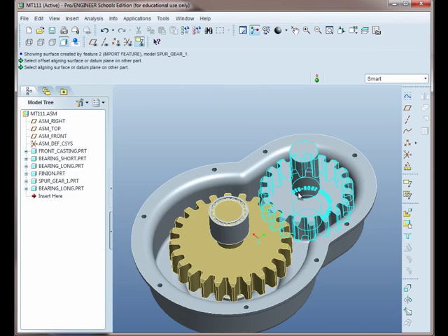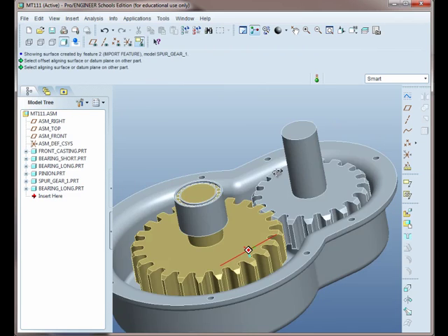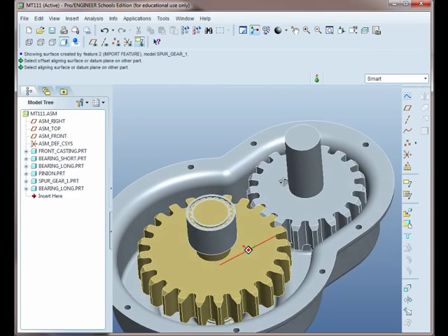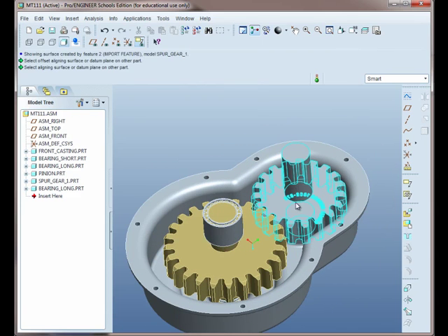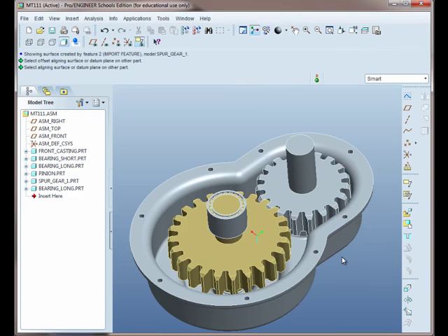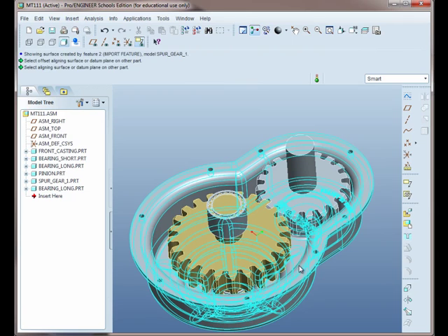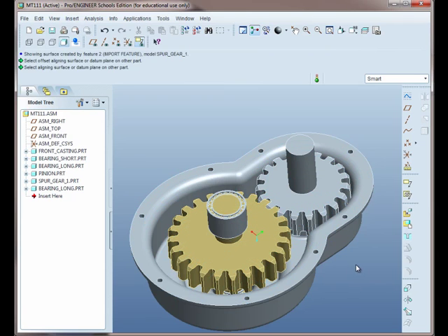The other bearing will drop in once we have the rest of the assembly surrounding it, because that one actually darts out a little bit out of the surface of the casting that we'll create. Okay, the next item of business is to actually create a gasket on this surface. So we could use the top-down method of modeling, and that's found over here under Create.